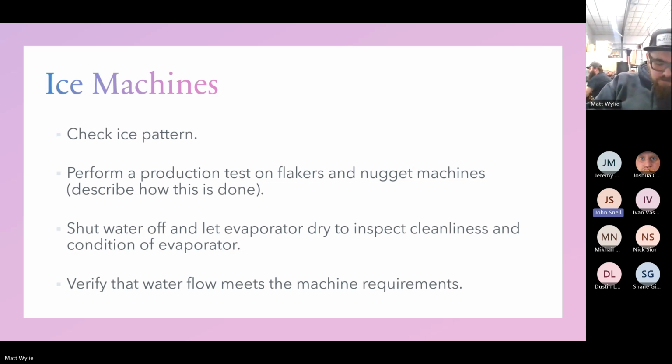deli and dairy. We had an instance where we thought we had plugged honeycomb because the coils kept freezing. Well, we ended up taking the whole back wall off because the coil was in the back wall, and we found old expired food, some of it 7 years old, that had fallen back, product that was on top: cheese, bacon, sausage. It was pretty gross, and it had restricted airflow, and that's why the cases were freezing, because it was off-cycle defrost, baffling a lot of people.